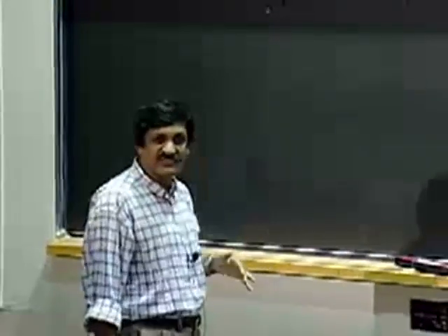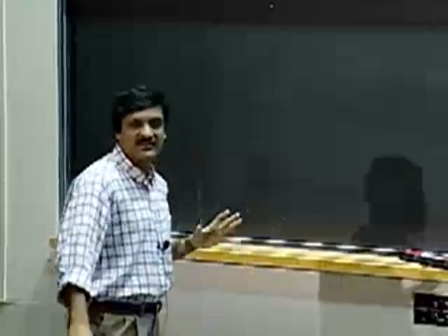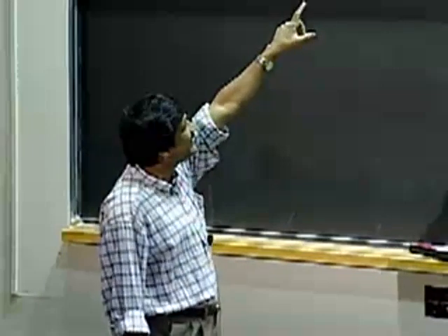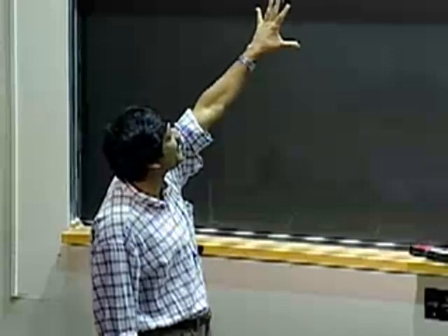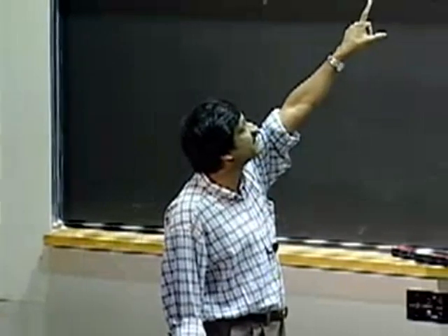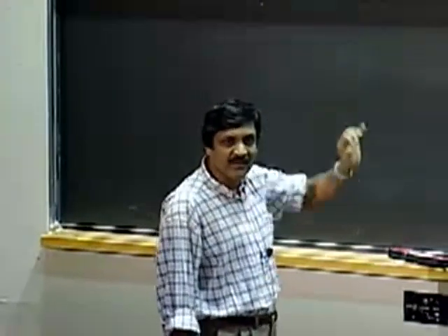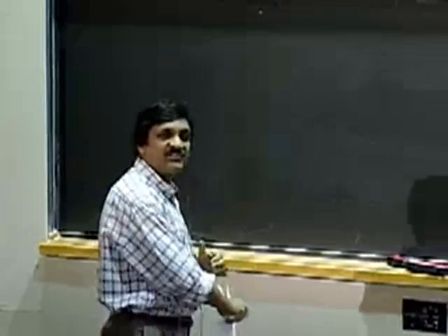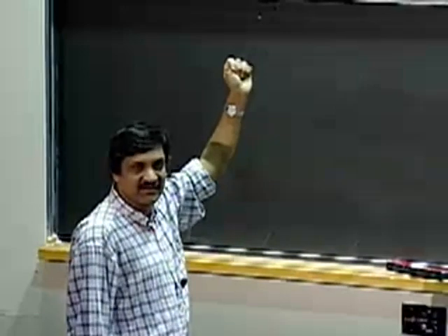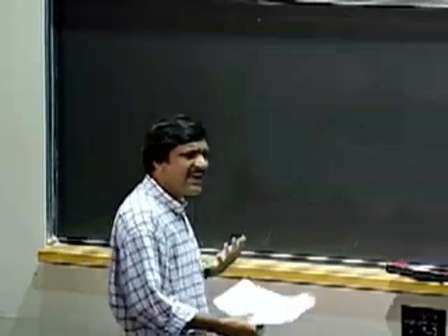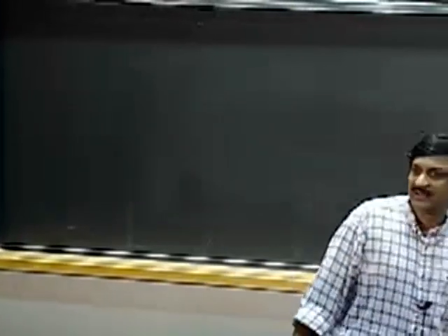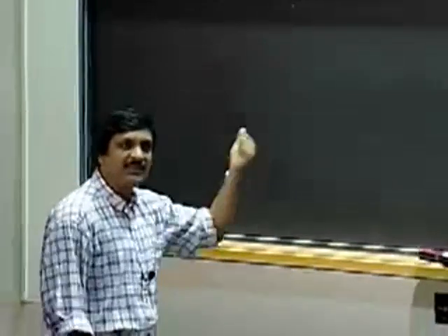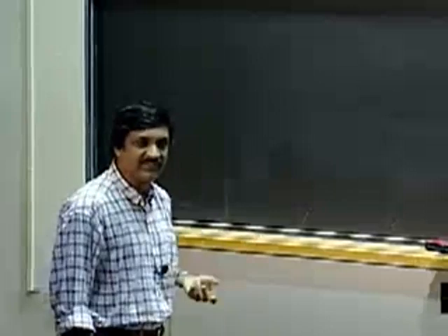Okay, so that's where the insight begins to show that if everything were magical, and I could somehow exactly keep things just so, that will be true. I will be able to build a positive feedback circuit where the output is equal to R2 divided by R1 V in. But remember, even the slightest amount of perturbation is going to send the op amp scurrying off to the positive rail or the negative rail. So how do we analyze that? How do we analyze the behavior of a circuit that, based on a small perturbation, begins to move one place or another? We want to analyze the dynamics of the op-amp.